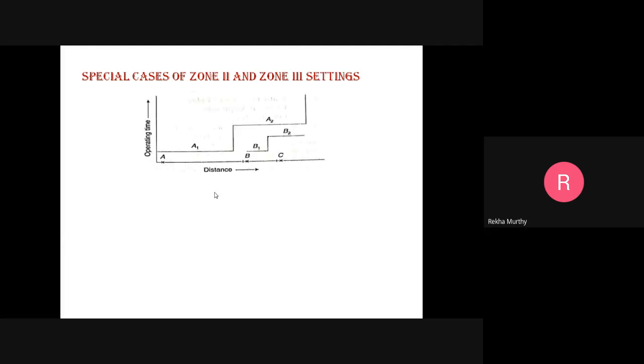So in this diagram, this is what the second zone adjustment has been done with the additional time for selectivity with the relay of the very short adjoining line, which you can see here. Earlier we had considered 80 to 90% of this, so now it has been increased further, and this was around 50%. Again, you can see there is a small change, and it is almost covering up